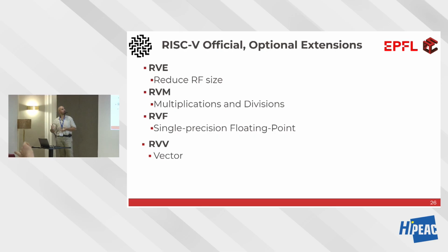So your colleague is saying no, because maybe the other CPU doesn't have the M extension. And why doesn't it have the M extension? Because extensions are not mandatory. That's what I want you to take home. Is it possible for the CPU to trap and have the OS go in with a handler and do multiplication in software?